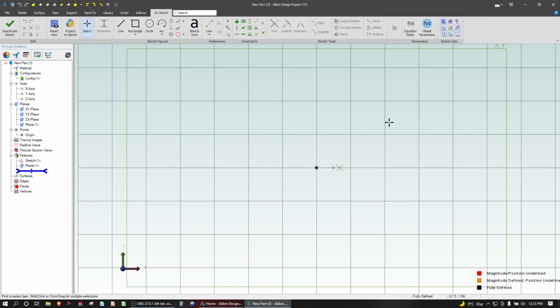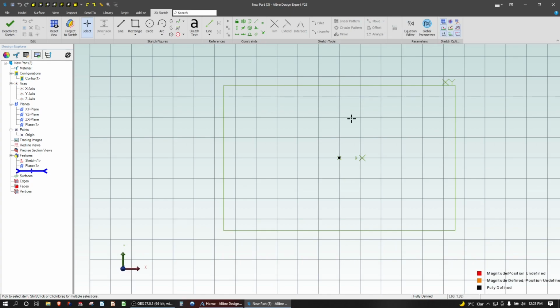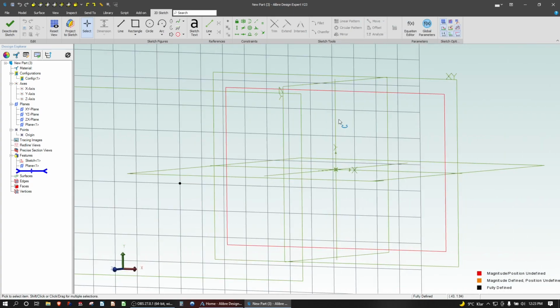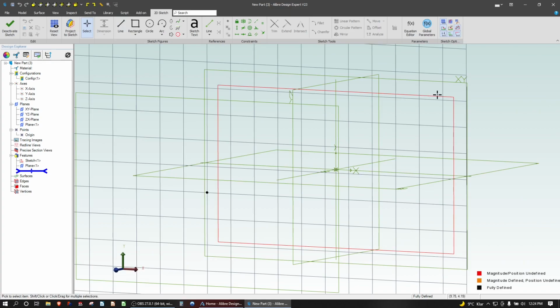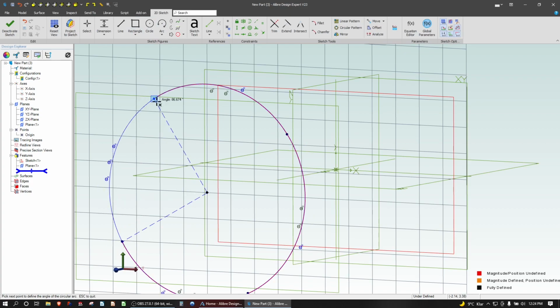Now, in a lot of CAD platforms, it's best practice to go same number of sketch elements to same number of sketch elements, right? So we have a line, line, line, line. That's 4 lines, so we need between a loft to have another 4 sketch elements. So if I want to go to a circle shape, to a square shape, I may feel more inclined to make 4 arcs, and that way we can go 4 vertexes to 4 vertexes, and it makes the loft pretty clear. So let's try it and see what happens.